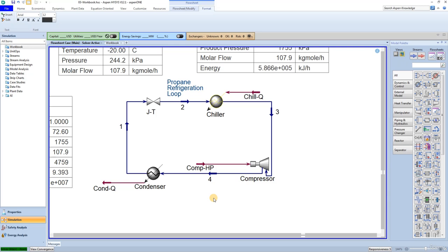Templates provide a mechanism by which two or more cases can be linked together and also provide a convenient method for breaking a large simulation into smaller, more easily managed portions. Before converting a case to a template, it is a good idea to make it generic so it can be integrated seamlessly into other processes.